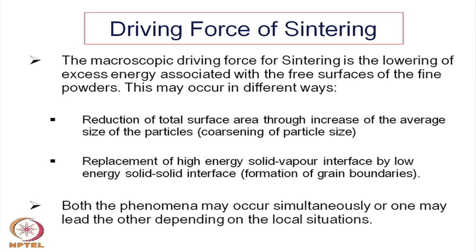So, by that process also it can reduce the surface area and surface energy term. This is one of the ways to look at the system where the particle size is just growing, but the interparticulate bonding is not really taking place. So, if this kind of process happens, somebody takes just the loose powders, not compacted powders